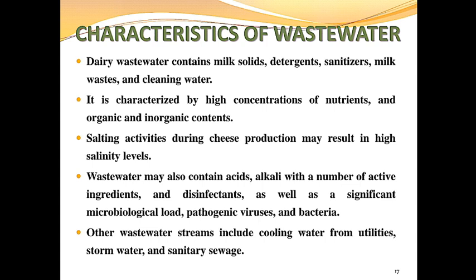The dairy wastewater contains milk solids, detergents, sanitizers, milk waste, and cleaning water. It is characterized by a high concentration of nutrients and organic solids, also inorganic solids. Salting activities during cheese production may result in high salinity levels.